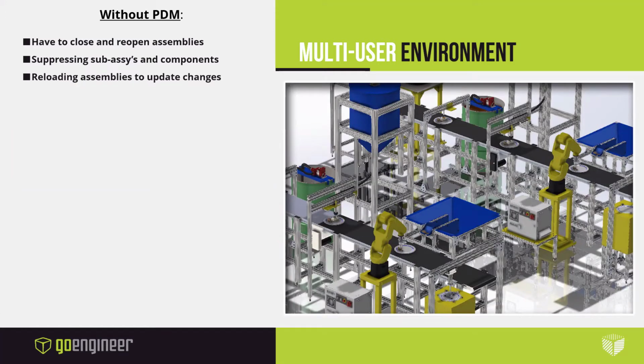The last one we had was the reload capability, being able to right click on a part and say reload. There was a little checkbox that said reload it read only, and then that would release it as well. That one was a little bit quicker because it was pretty instantaneous. But if you're working on a massive assembly with subassembly and subassembly and parts, sometimes it was easier just to save it all, close it down, let them open what they needed, and get back into it.